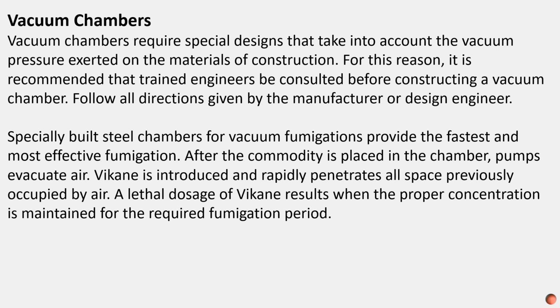Vacuum chambers. Vacuum chambers require special designs that take into account the vacuum pressure exerted on the materials of construction. For this reason, it is recommended that trained engineers be consulted before constructing a vacuum chamber. Follow all directions given by the manufacturer or design engineer. Specially built steel chambers for vacuum fumigation provide the fastest and most effective fumigation. After the commodity is placed in the chamber, pumps evacuate air. Vikane is introduced and rapidly penetrates all space previously occupied by air. A lethal dosage of Vikane results when the proper concentration is maintained for the required fumigation period.